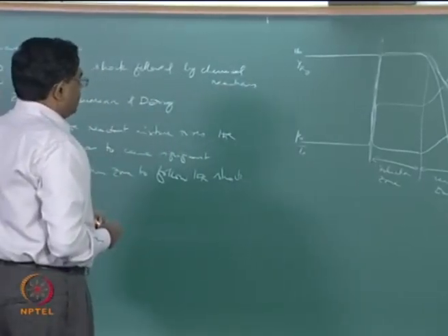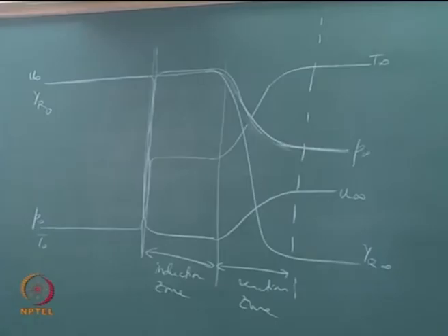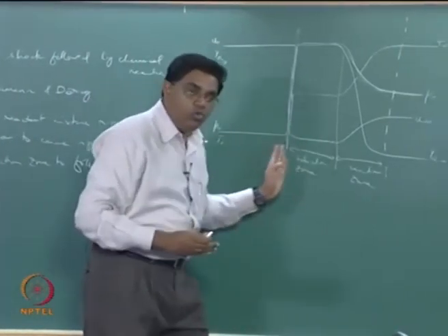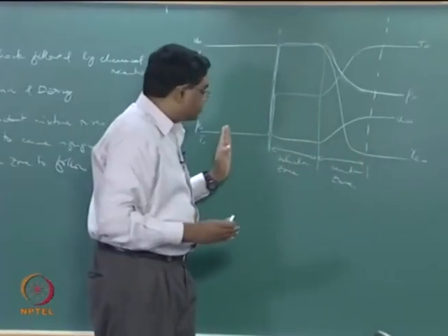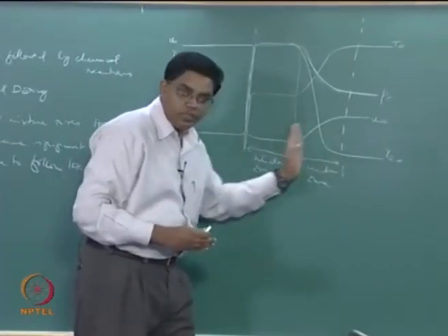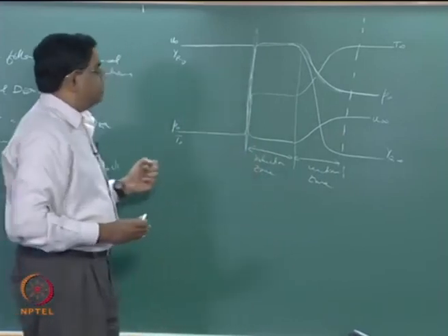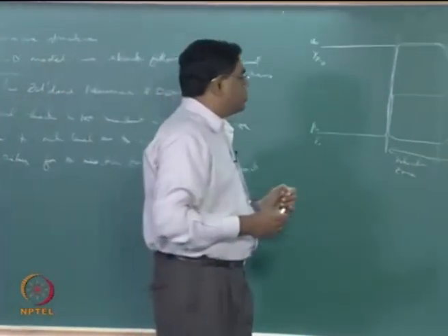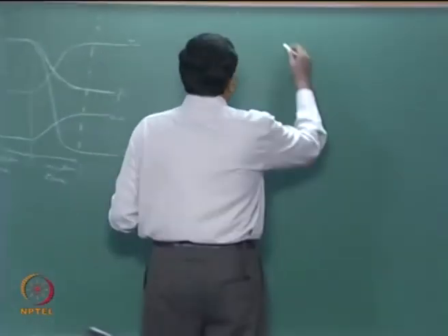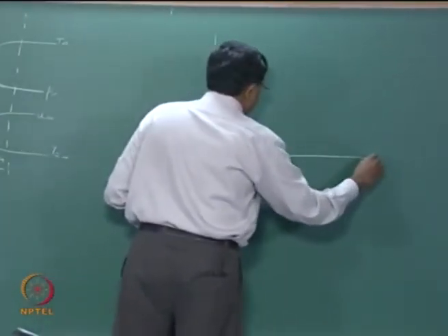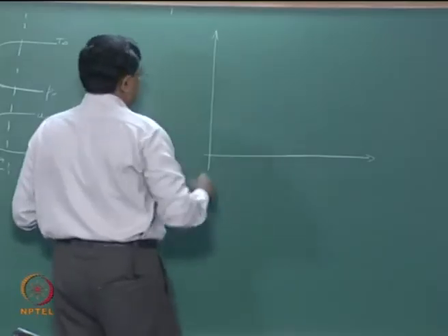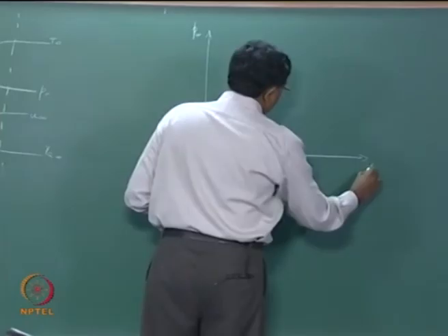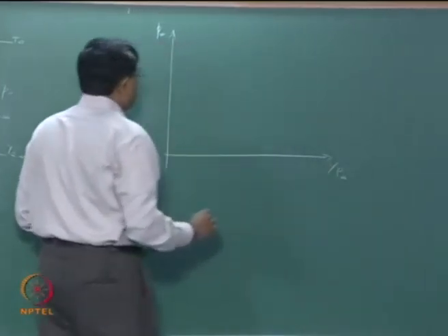So can we now think about how the state of the gases moves through the reaction, the detonation wave thickness within a Rankine-Hugoniot framework? If I want to do that, let me plot my Hugoniot plot, where you have P infinity and then 1 over rho infinity, which is what is classically plotted.